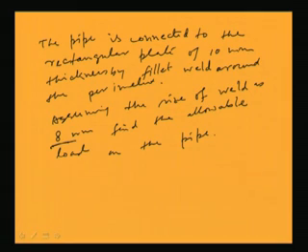Weld size has been given. Now we have to find the solution. Solution means we have to find the value of P. That means we will try to find out the different types of stresses at different points, then we will find out the worst condition.